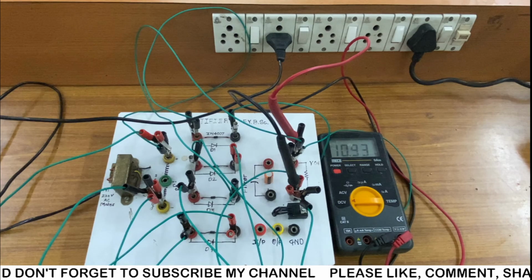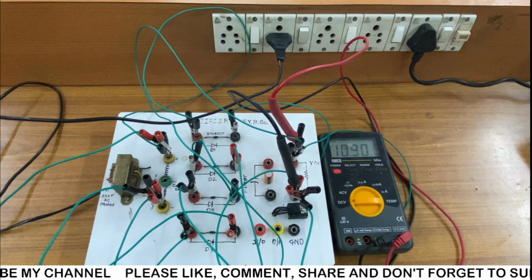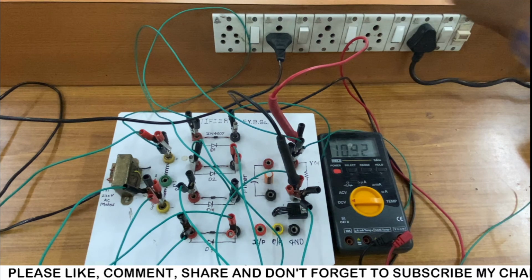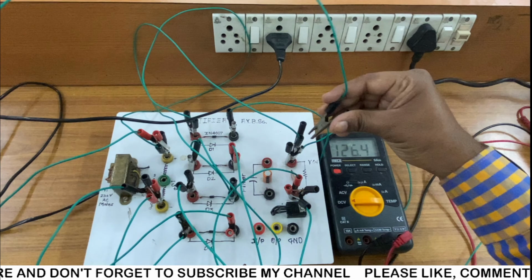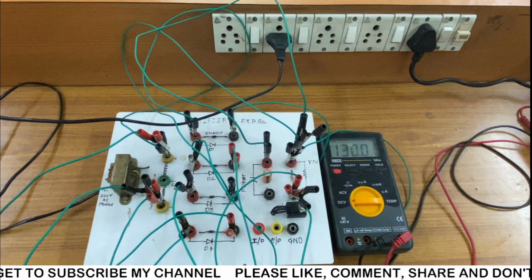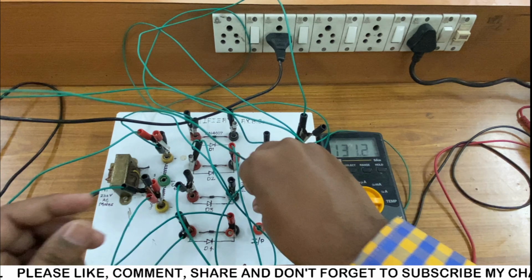So to have a C filter, again the same procedure as for the half wave rectifier and the 2 diode full wave rectifier. What we have to do, we have to connect the filter circuit. So I am going to switch off the socket, then I'm going to remove the multimeter from the connection. I'm going to take a wire that is connected in between resistance RL's one terminal and the capacitor. Then again I'm going to take the next cable. I'm going to connect it in between resistance RL's next terminal and the capacitor. So now the circuit is perfect for the with C filter bridge rectifier.